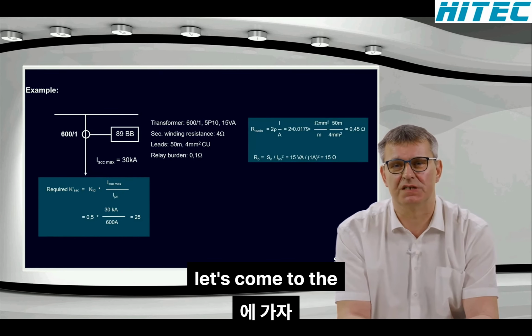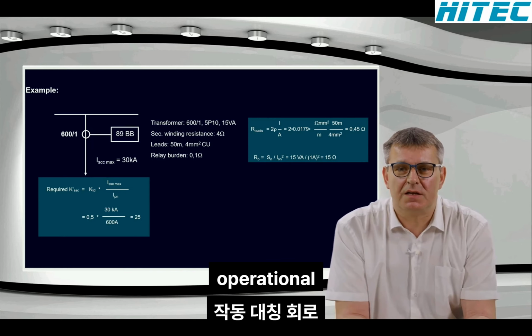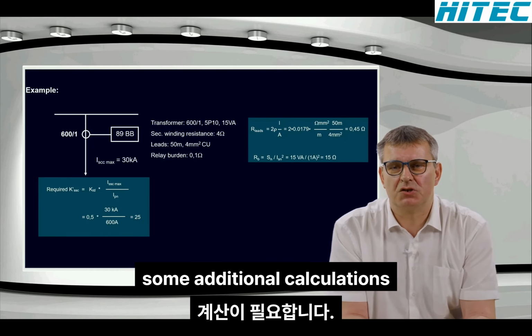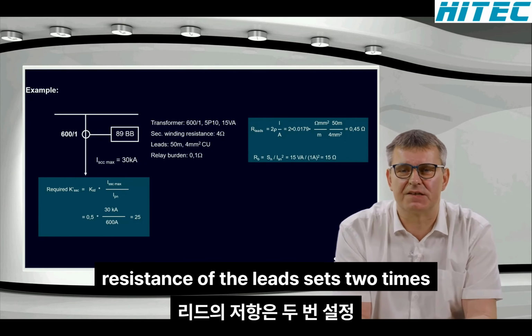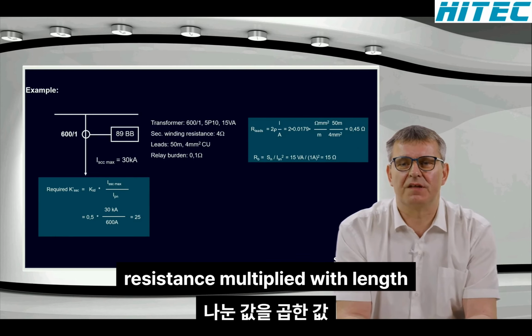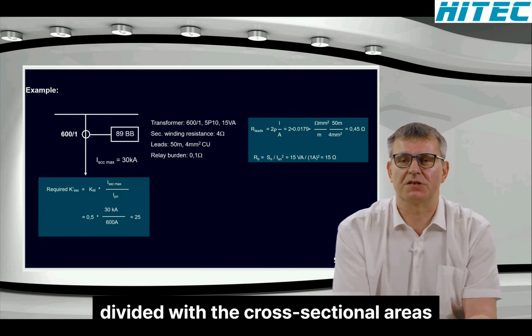Let's come to the operational symmetrical short circuit factor. Here we need some additional calculations. The resistance of the leads is 2 times the specific resistance multiplied with the length divided by the cross-sectional area.